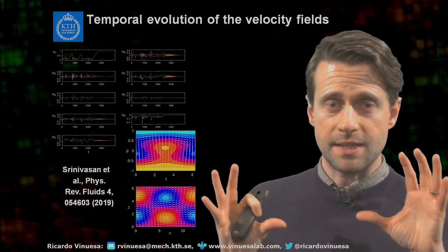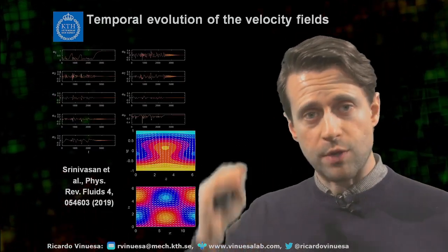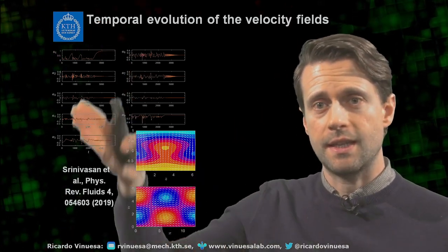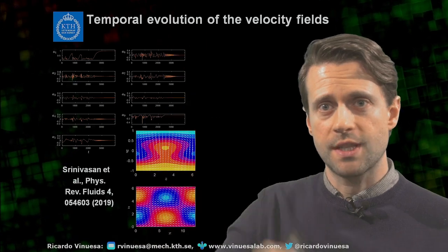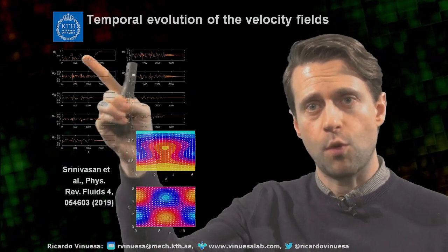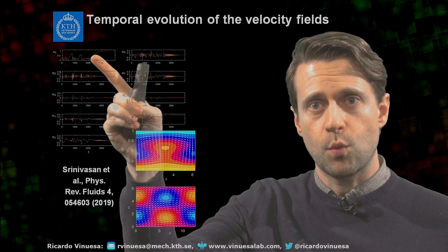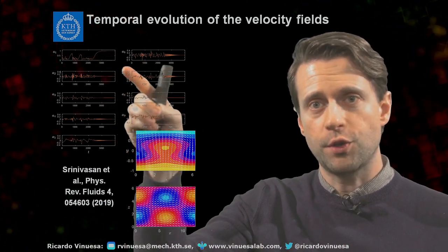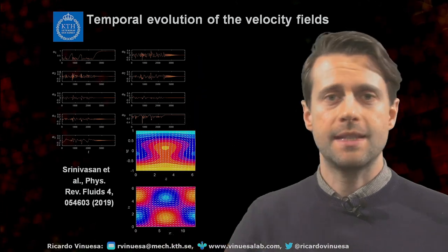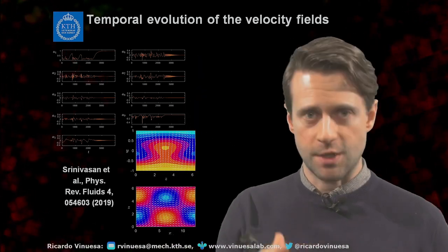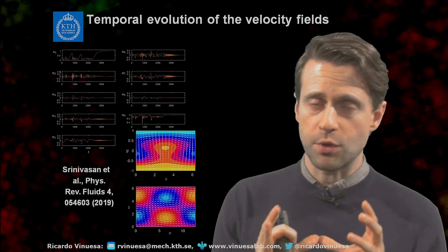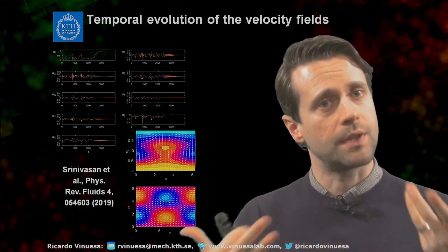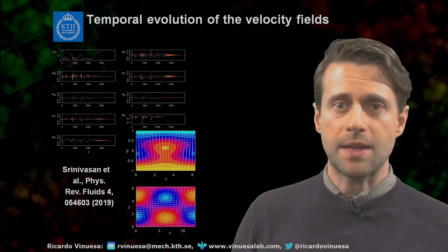So this is basically what the data looks like when we are integrating in time this 9 equation model. So here you can see the temporal evolution of the 9 coefficients, starting from the first mode. An interesting thing is when the first mode takes a value of 1, which is constant, all the other modes go to 0, and that's essentially the case where you have relaminarization. In our data set, we're going to avoid relaminarization because we want to focus on the turbulence part of the flow, essentially. And that's what the flow looks like.